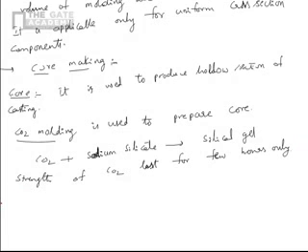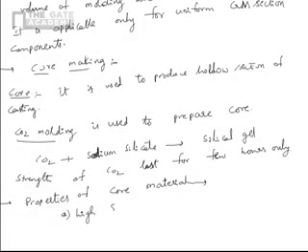So the properties of core material are: it needs high strength, to withstand the buoyancy force of the molten metal; high collapsibility, it has to be easily breakable; and free from moisture.